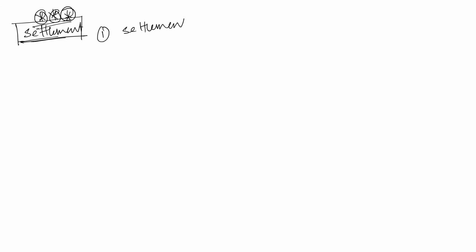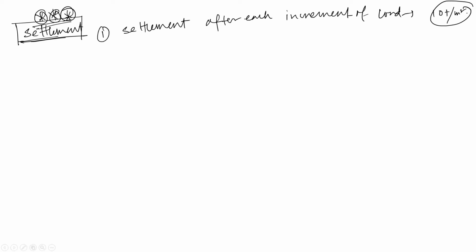Now the most important thing is this settlement. This is the most important thing. My humble request, please be concerned when you see that settlement part. Okay. First, observe the settlement after each increment of load. Which load? That starts from 10 ton per meter square, right? Okay. And there should be some interval.